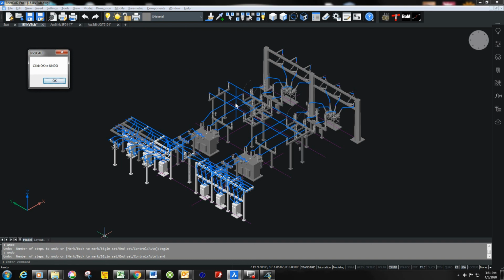So you can see here, somebody's not connected this bus in over here, so we've got a problem here. But you can see all of the bus. These are all the lines that are on the X-bus layers, the various X-bus layers, and you can see all through here that they're all highlighted. So this is a good indication that you've got a good handle on the total amount of bus you need, except for this that's missing here.